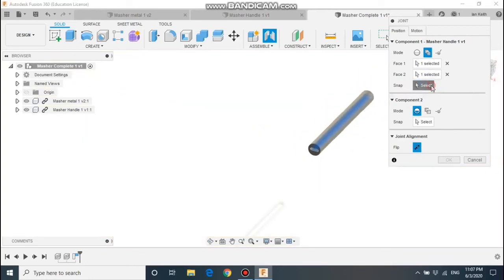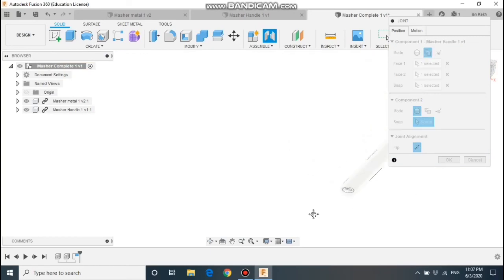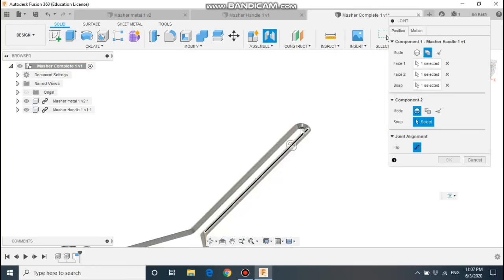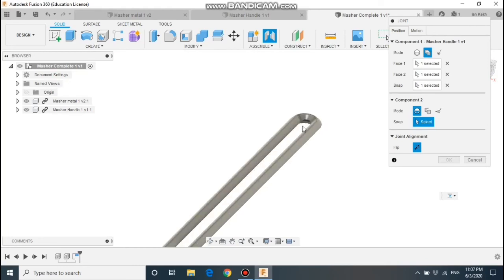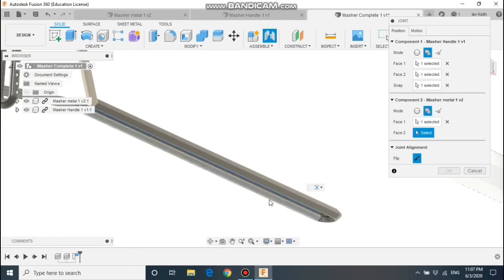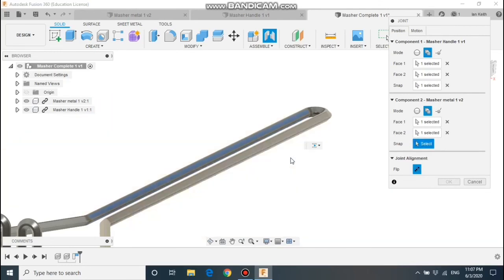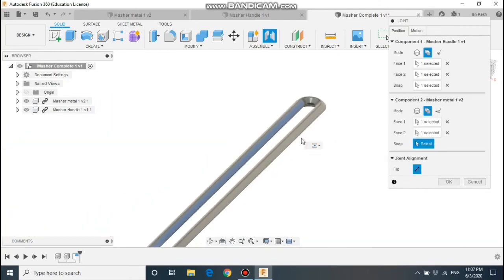And then the snap position I'm going to select just now is going to be on the work plane in the center, if I can get it. There we are, on component 2. Again, there aren't lots of options, no flat surfaces really. The 2 plane option once more though, so I'm going to select the top surface here, bottom surface here, and the snap position. Now I want to just rotate it round, get the work plane, and I'm looking to snap it in the center so it matches up with the snap from the component 1, the handle. I think that's it there.